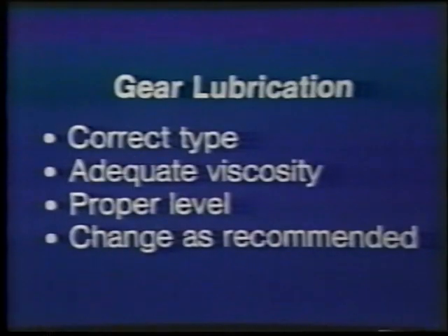For example, inadequate lubrication can cause frosting and pitting to advance to a more severe stage instead of healing over. Because of this, it is extremely important to use the correct type of lubricant. Be sure it is of adequate viscosity. Maintain proper lube level, and change lubricant at recommended intervals.